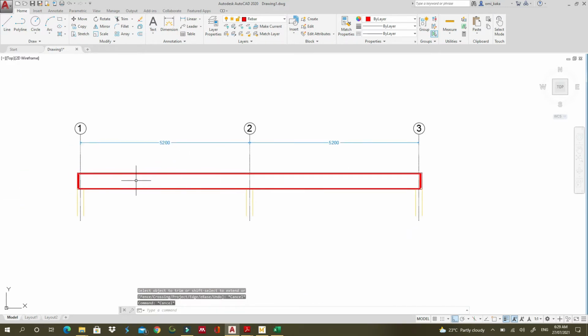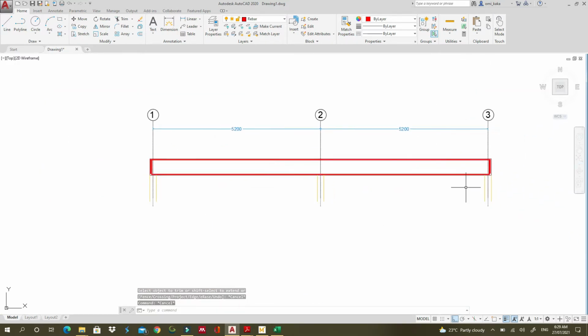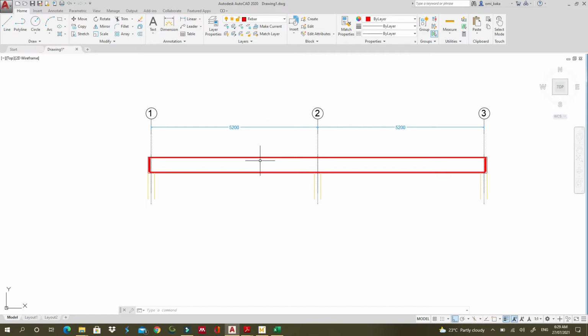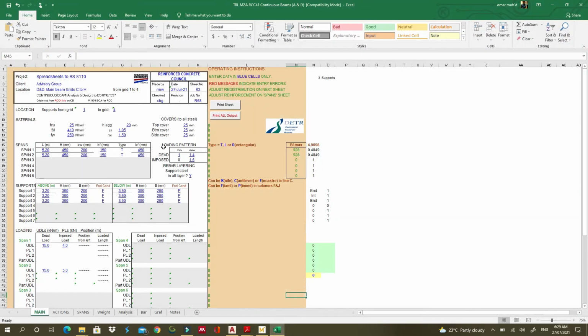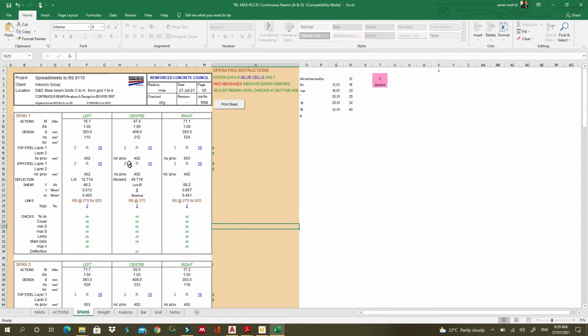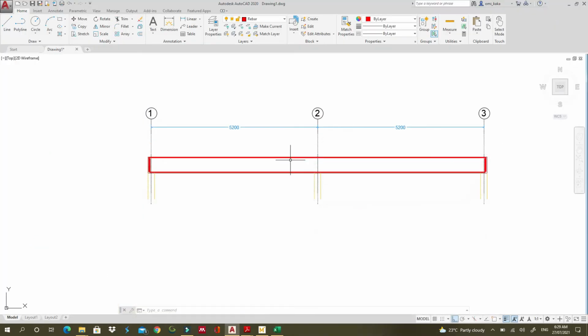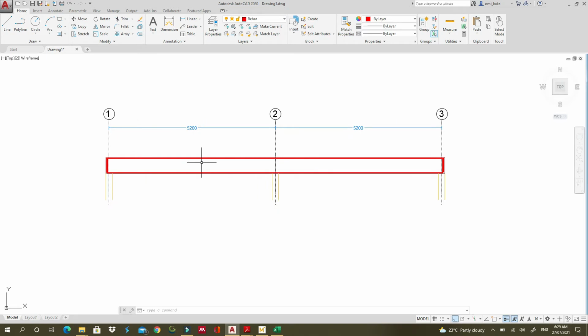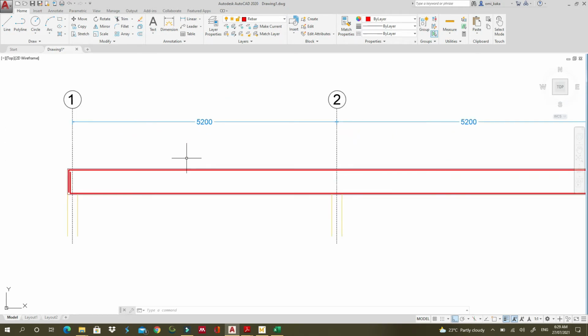Yes, just like this. So as you can see, right now we already have our rebars. What we need to do now is, as I said earlier, I will use 3 bars here and 3 bars on the mid support. What I'm trying to say is there will be 3 Y16 here, 3 Y16 here, and 2 Y16 here, and 2 Y16 here. And 3 here. I did that because I want to show the curtailment, and this is very important, guys.